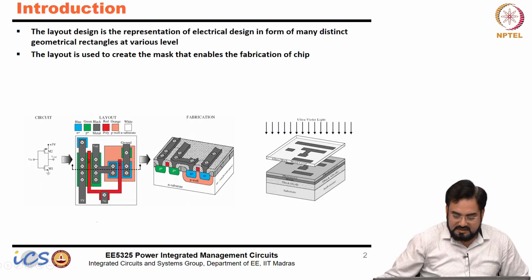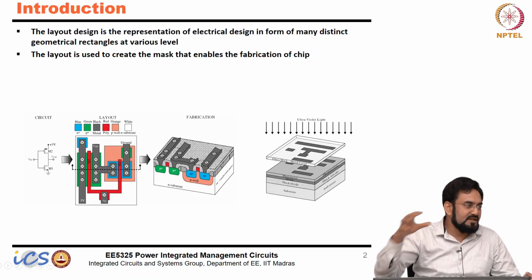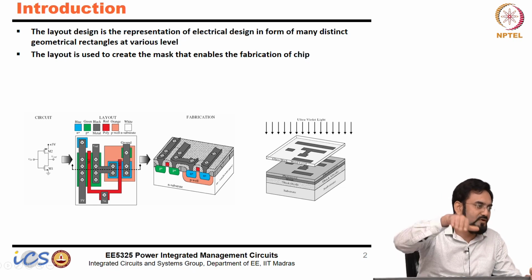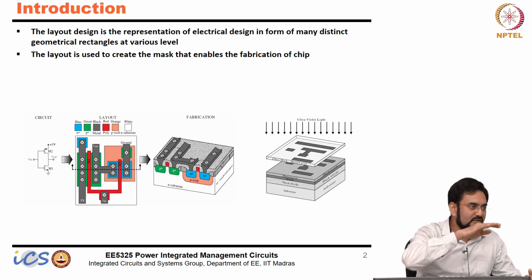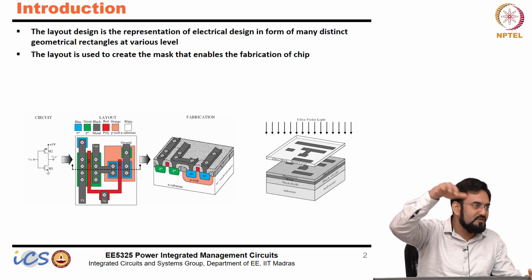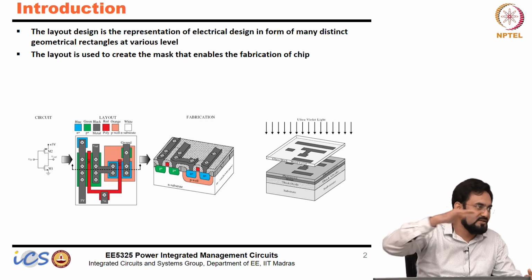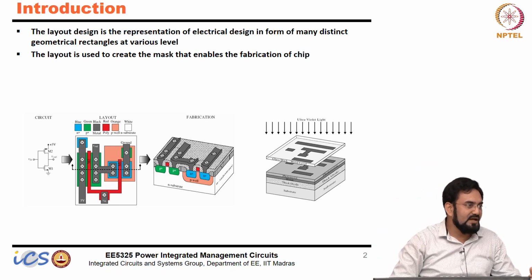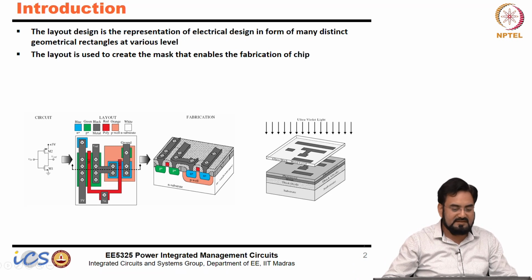That's it. Okay. So, any device, if you look at how the device gets fabricated, you have a substrate, and on that you grow different layers. You grow your diffusion for the well, then you grow your source and drain, poly, gate oxide, everything, layer by layer, and when you complete everything, it will give you this structure. Okay, this is the cross section. So, this is your substrate, then you have a P well, N plus. So, this is your N channel MOSFET, then this is your gate.